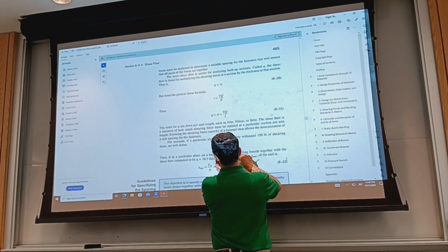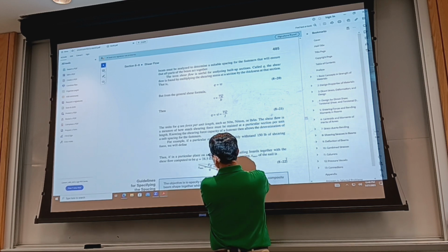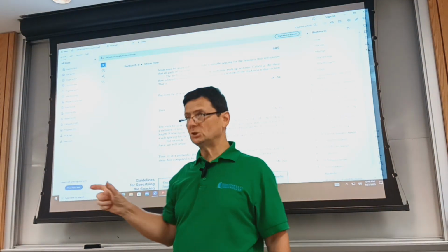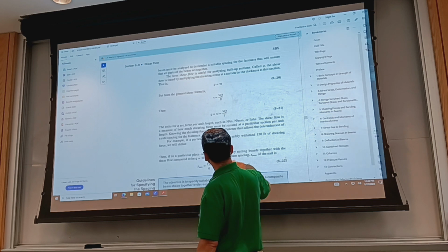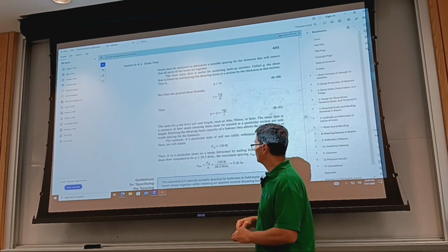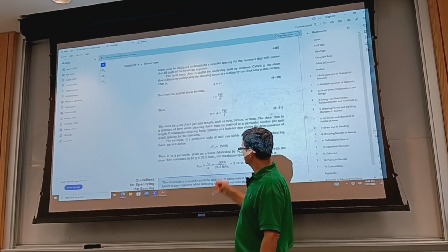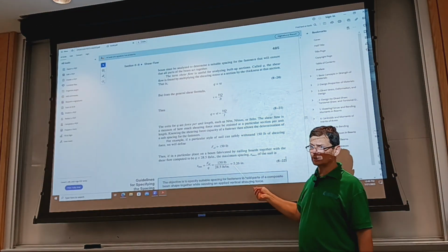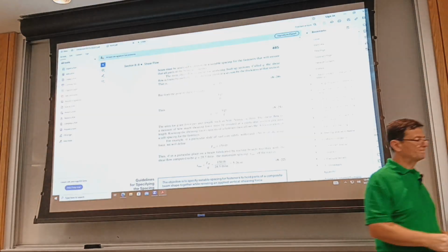So you have the allowable force per fastener, and you have the shear flow. It gets you the maximum permissible distance between two successive fasteners. If you take the allowable shear force per fastener and divide it by the shear flow, calculated with this equation, it gets you the maximum distance. And of course, you round it to a preferred size. This one very well can go to 5 inches.